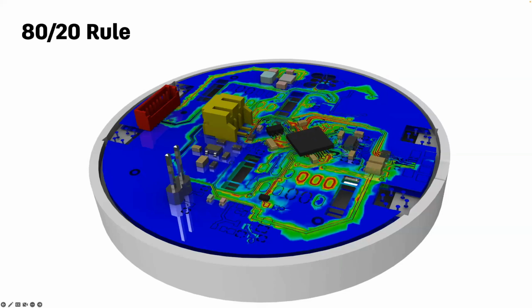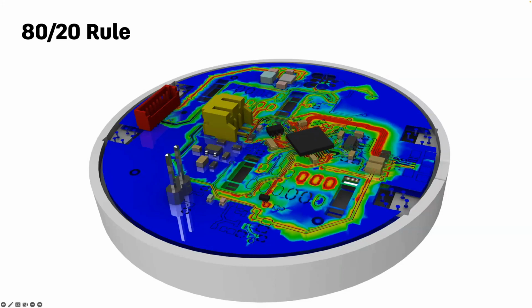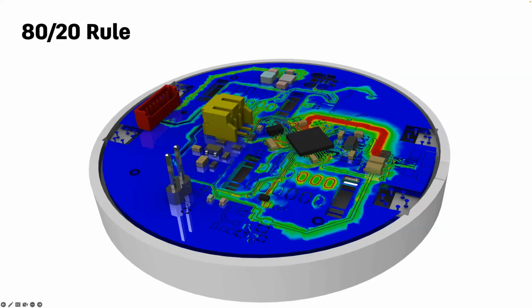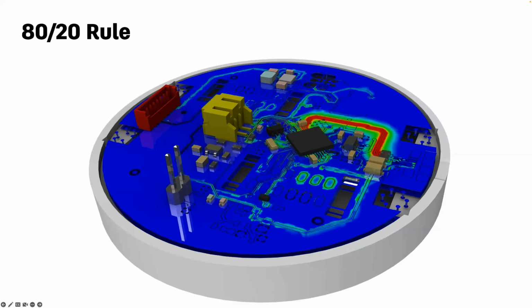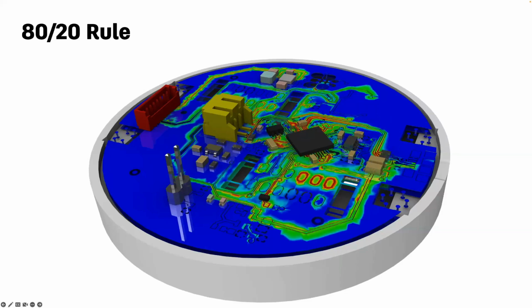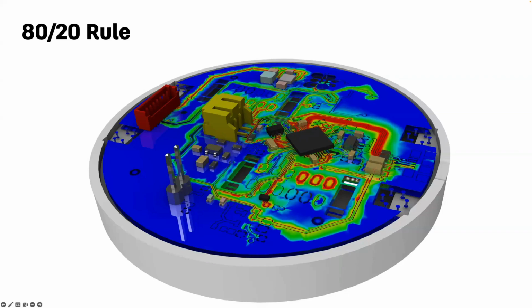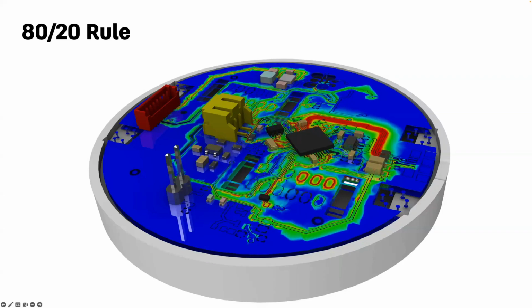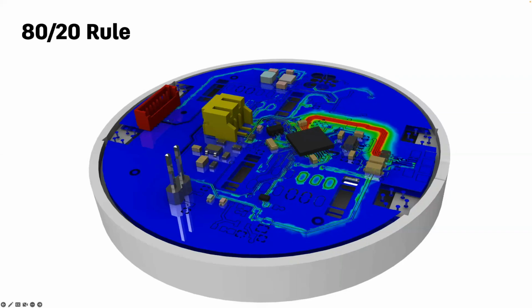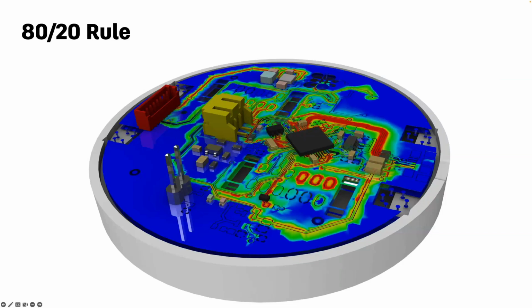The extension is going to show you where you have impedance discontinuities and what the time delay is of your traces. Knowing impedance and knowing time delay, you electrically know almost everything you need to know about your signals. So with that said, I want to go over two very simple concepts, and that'll give a little bit of context to the demo.